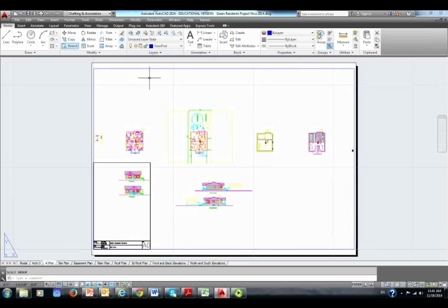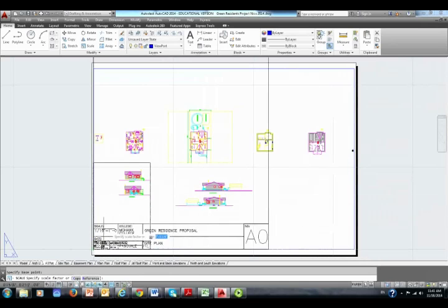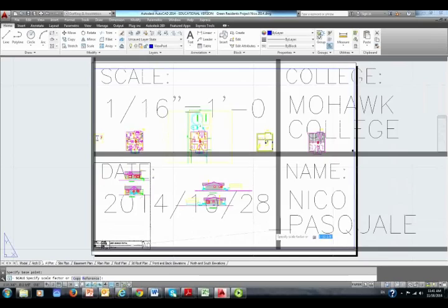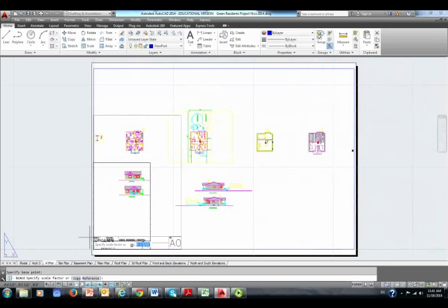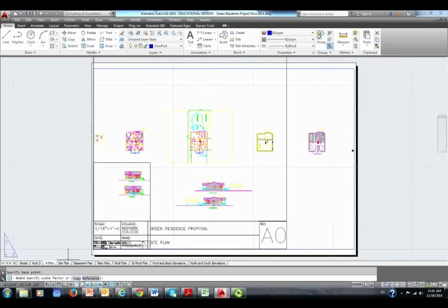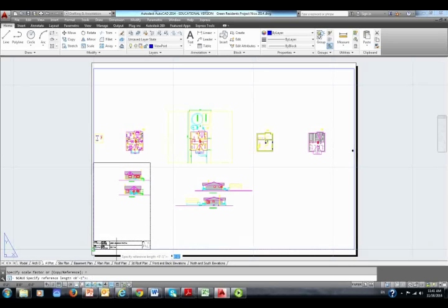Okay, let's do it again. Scale. I'm going to pick up all of the items in my title block, plus this line, enter. So it's very, very important that we pick up this point accurately, but we need to see where we need to go. So you see, if you don't know the scale factor, then you're kind of fudging it. So what I'm going to do is guide you to, notice here, you have an option for R for reference. I'm going to type in R for reference.